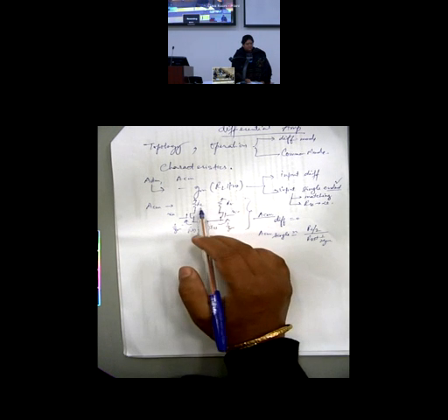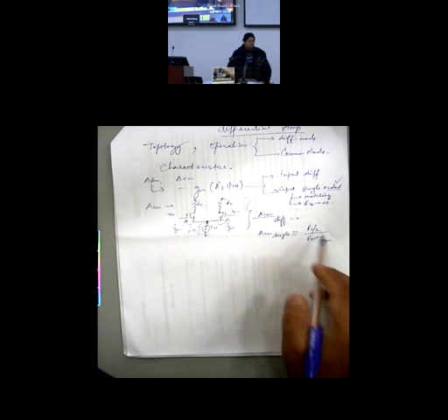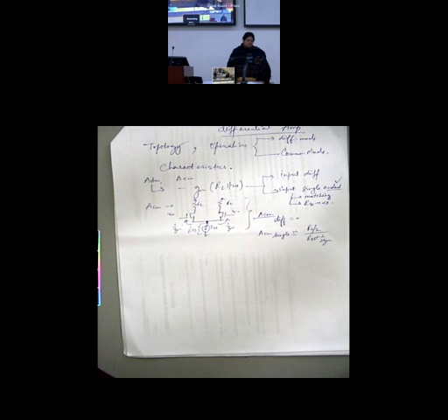Okay, and similarly RL by 2, they come in parallel, that comes out to be RL by 2. So this is the expression of ACM, a very shortcut method. We have made approximations here. What are the approximations? RO is high and RL is smaller than RO. Under these approximations, and we are neglecting GMB, that is negligible, we are getting an approximate result.